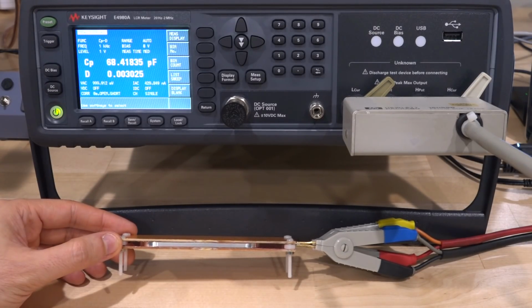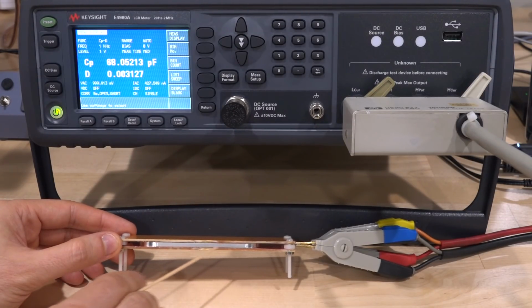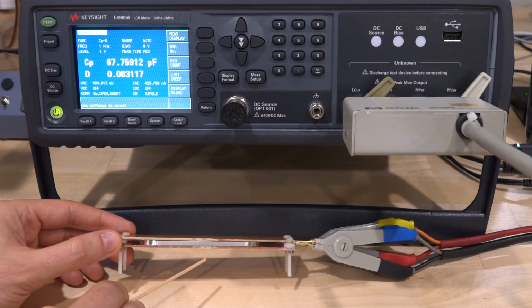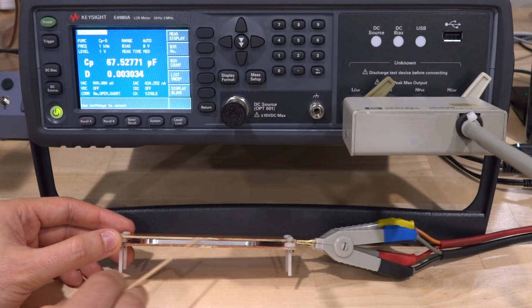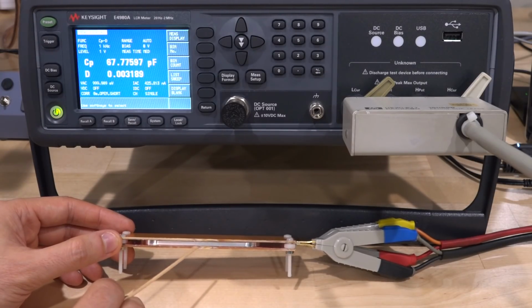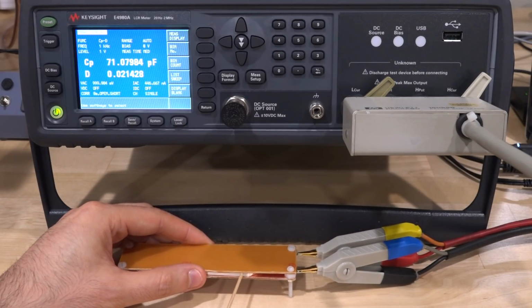So basically what you have is a capacitor at the top from the plate to the top of this plate with only the tape in the middle being the dielectric, and then another capacitor at the bottom identical to the other side. There's a bit of stray on each side as well. Those two capacitors are actually in series, so the total value of them is smaller than each of them. But because the dielectric is so thin now, the capacitance is so much higher, and we've reduced the total amount of gap so much that now the total capacitance is significantly higher than it used to be.